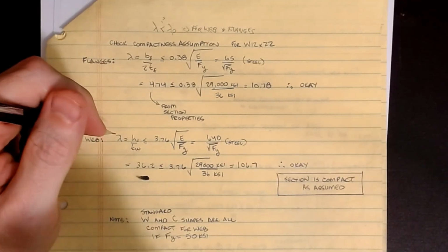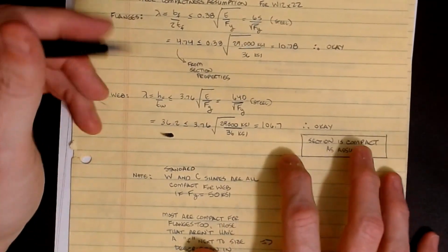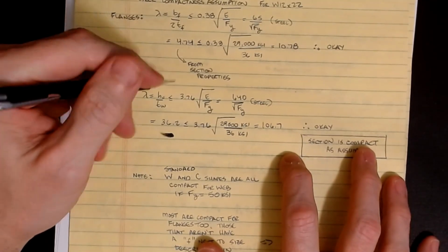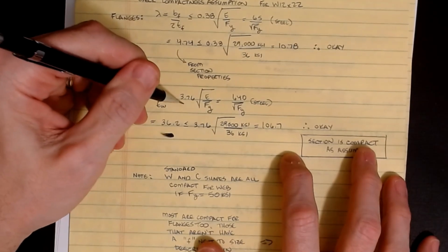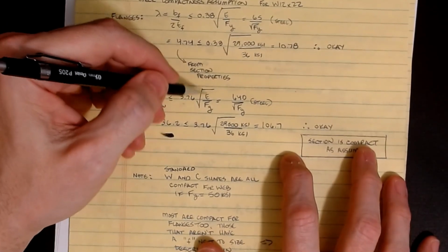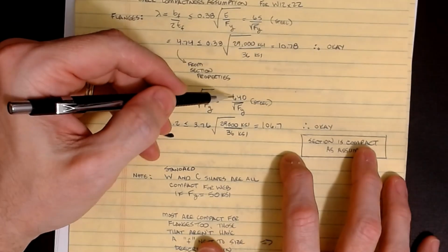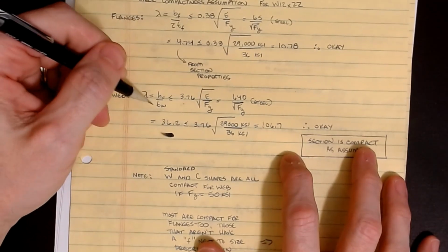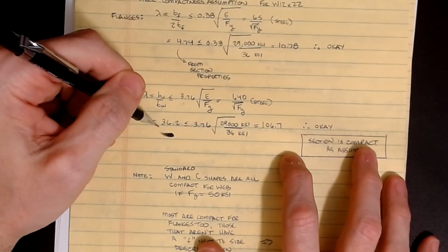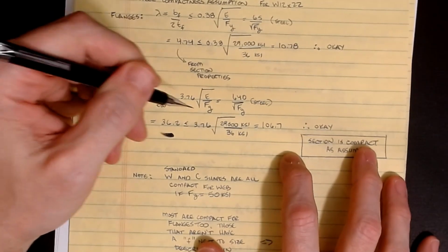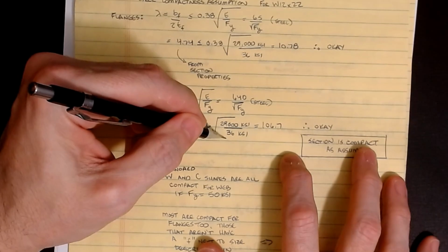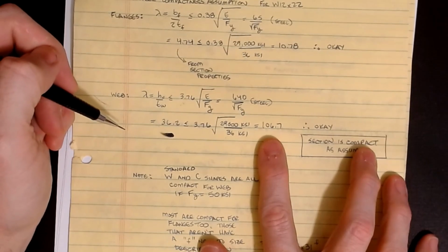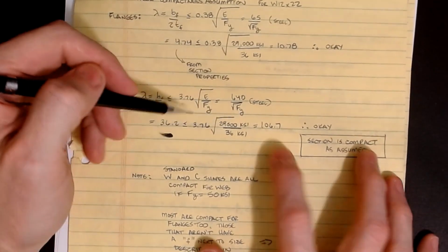Generally, if you're okay for the flanges, a lot of times you're okay for the webs on the standard shapes. Now for the web, we're going to check lambda equal to h over tw. For lambda p, that's the 3.76 formula, square root of E over Fy. If I do the math and simplify it, 640 over the square root of Fy for 36 KSI, for E of 29,000. My h over tw for this beam is 36.2. Again, that's from the section properties. And if I do this calculation with 36 KSI for Fy, the limit is 106.7. So we have plenty of room to spare on the web. Not as much on the flanges, but on the web we're plenty okay.